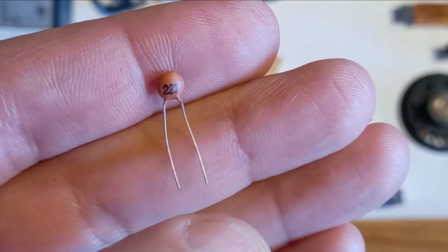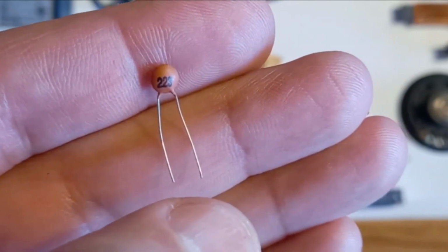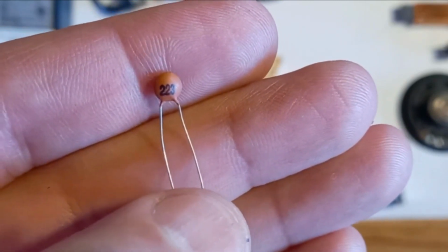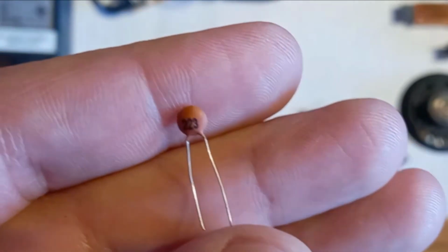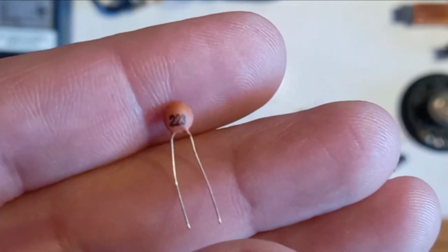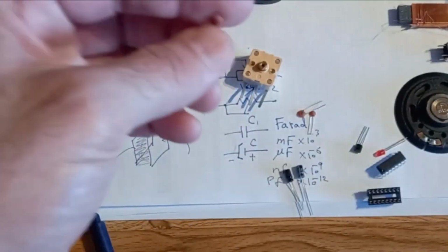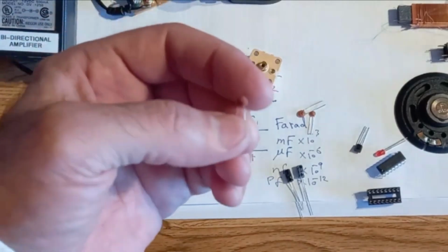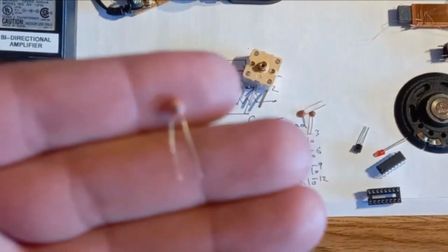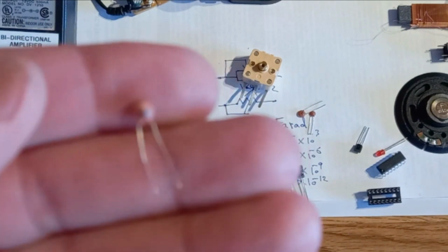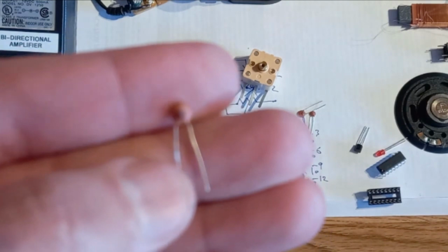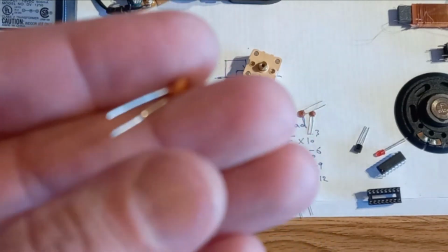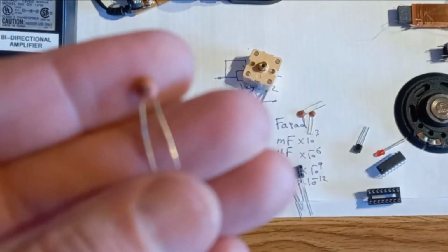That is 22, the same as resistors. The last digit is the number of multipliers or number of zeros. 22,000, but bear in mind, this is 22,000 picofarad. So it's always picofarad unless it's stated. Whatever the value is written on it, if there are no indications like a small m or micro or anything like that, then you have to consider that picofarad.